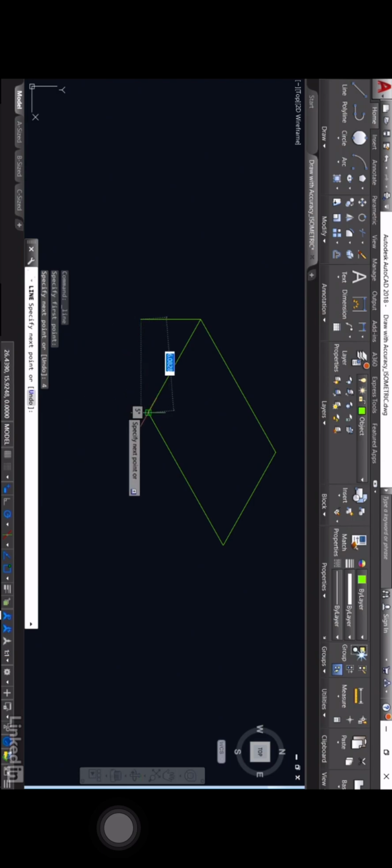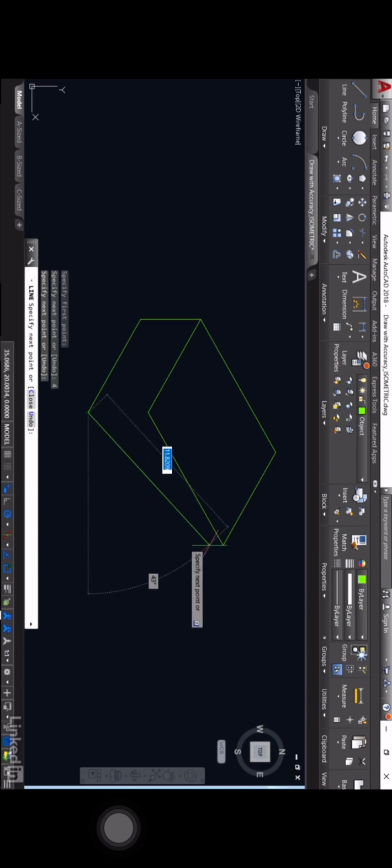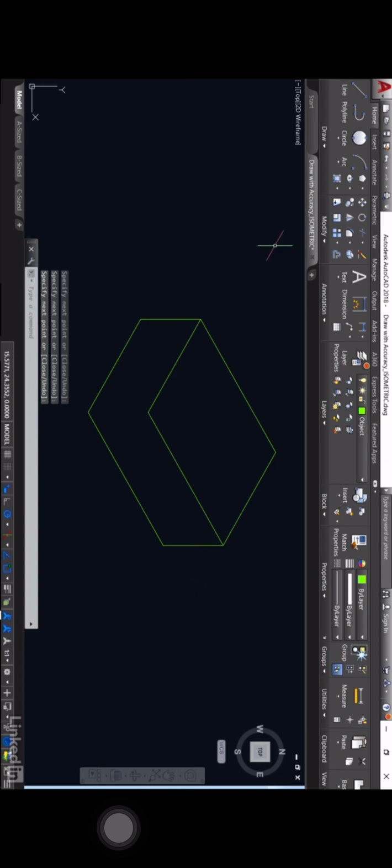So I can hover there and come vertically down and use things like object snap tracking. And as I come up this way, I've got the angle again, so I can hover there, come down this way, and it all snaps neatly at angles so that I can now draw my isometric view. So I've snapped to the endpoint there, press enter to finish, draw one more little vertical line from endpoint to endpoint, enter to finish, and there's my isometric view. So with that ISO drafting and the ISO planes, it's very quick and easy to create a nice little isometric view in 2D that represents a 3D object.